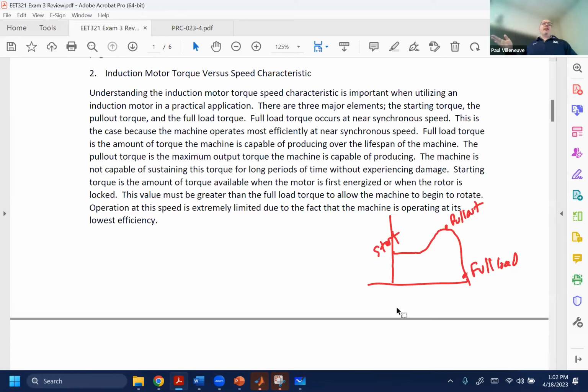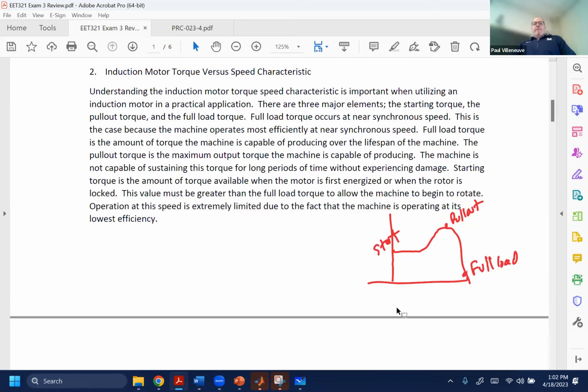We never think about it at voltage because you can easily get confused. The next time I say it's a leading power factor, you might say, oh, the voltage is leading the current. It's not that case. So always think about what current is doing. And Eli says in an inductor that the current lags the voltage. So it is a lagging power factor. Regardless of how much power it's outputting, it'll always operate at a lagging power factor.